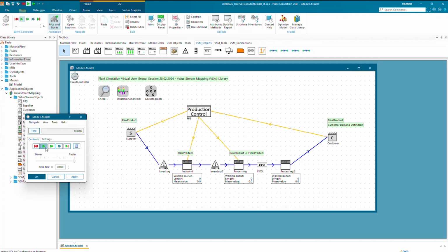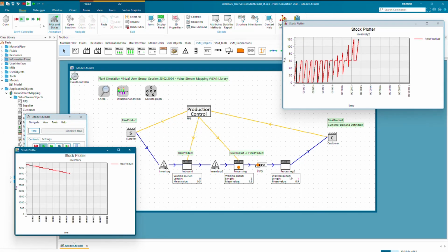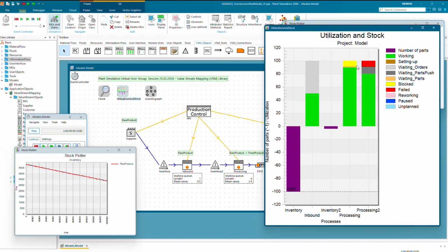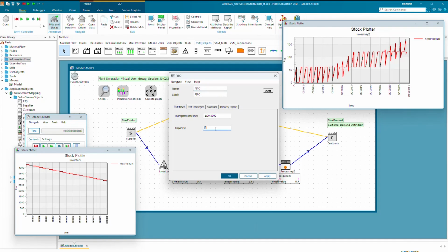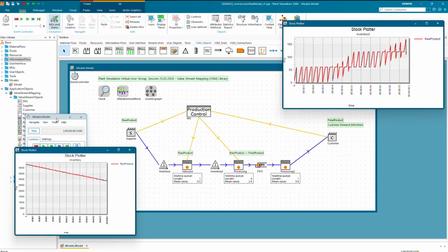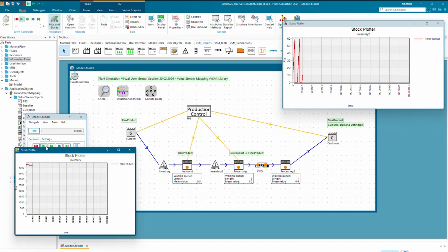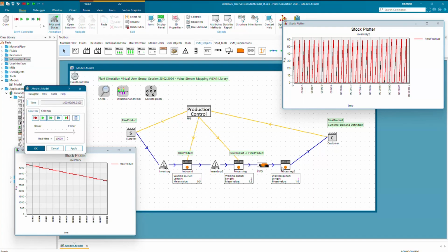If you simulate this, you basically have a push system right here, and due to failures and limited buffers you will see that inventory is piling up. You also have quite a high blocking percentage in the station. So it's the same experiment you would do with basic objects. Test increasing this capacity, maybe just to bridge certain failures, and to have a balanced system again. Quite similar then to Plant Simulation, once it is in the push routine.